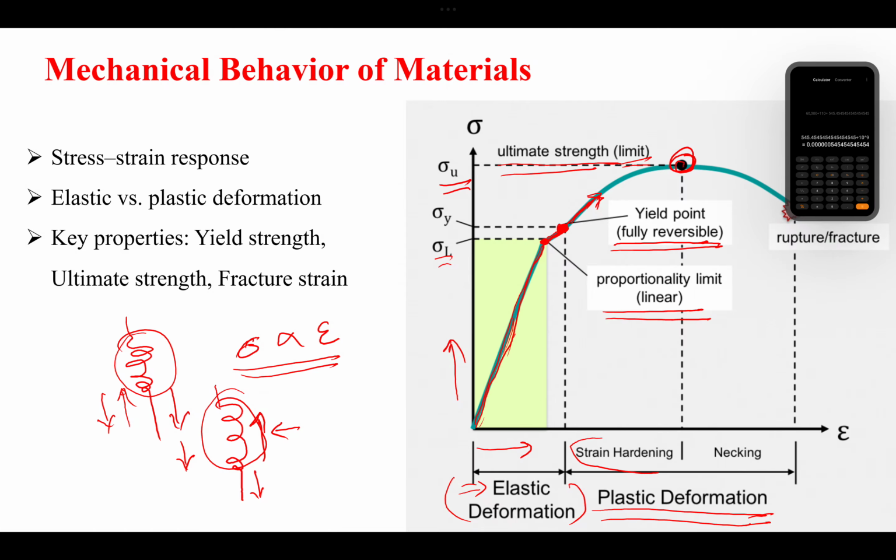And if you see, this region says strain hardening. That means the body is moving in a path where your strain is comparatively less to the stress. It's not less, but in the sense that it is not on the same route as it was earlier. So you are getting strain hardening, which means the curve is now moving up.